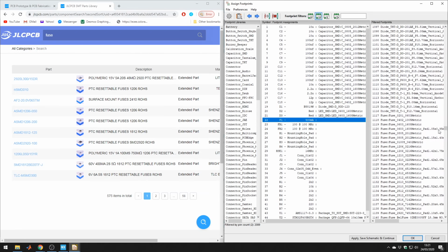So for the fuse, I think I have 0603 at home, so I'll just choose that. So that's potentially what to do. If there's extended parts I can easily solder myself, I'll just do it myself because it's not worth paying an extra €3.